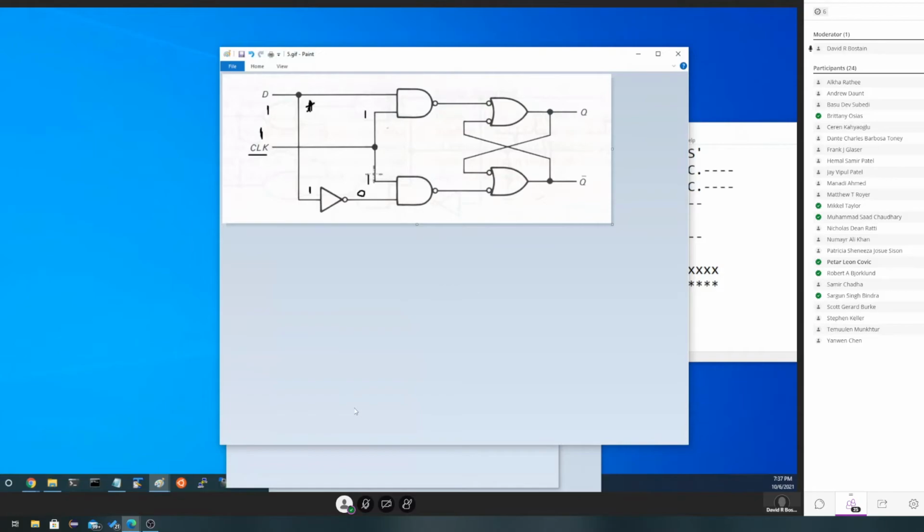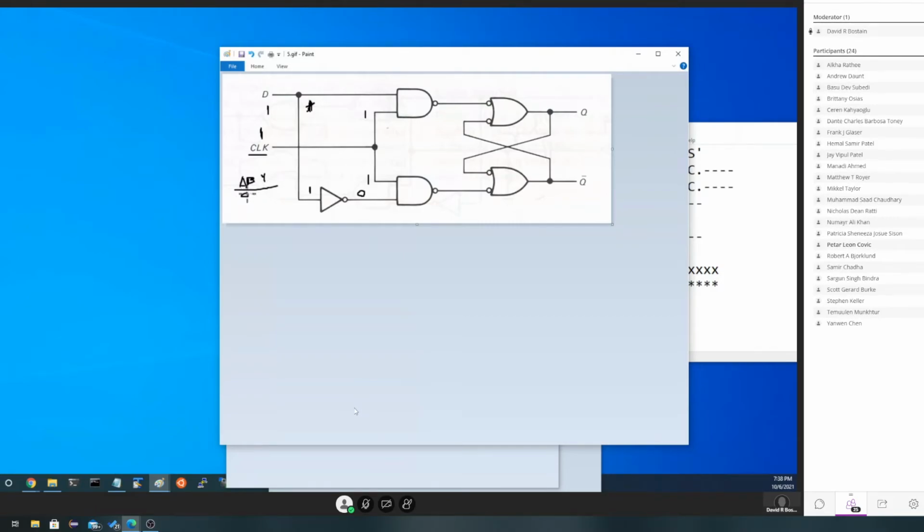So using a NAND gate, we write the NAND function over here so we have it handy. We've got 1, 1, 1, 0. So the only time to get a 0 out of this thing is if all of the inputs are 1, which in this case they are. So we'd expect a 0 here.